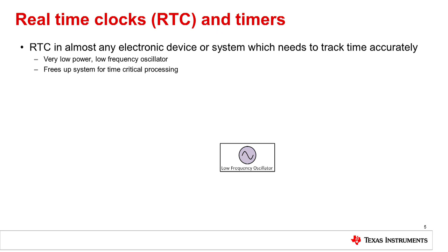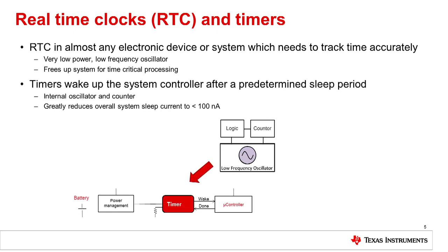Timers are used in many applications, but most commonly for battery-operated circuitry, especially when a backup battery source needs an extended life. No one likes to unexpectedly find a dead battery. For a timer, you add some logic to the internal oscillator, and a counter will count down the milliseconds or minutes. Once the counter is empty and the timer expires, a wake-up signal is provided.